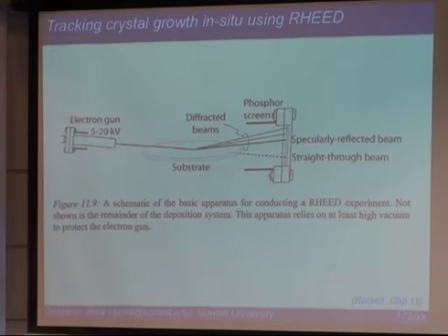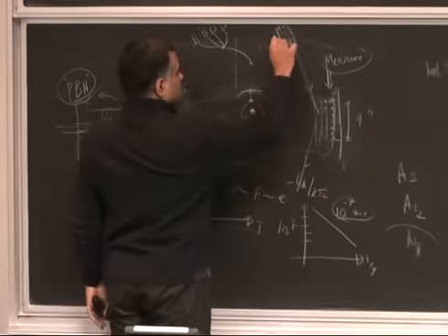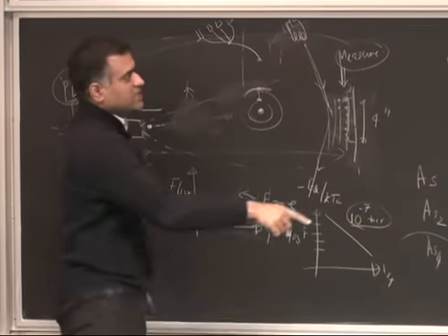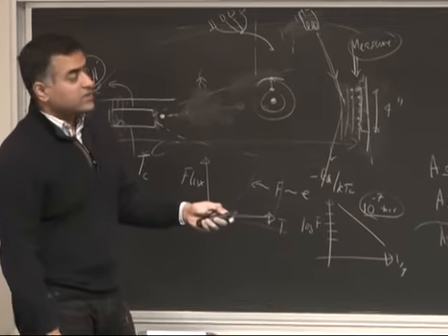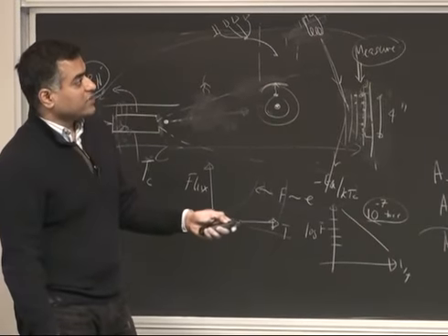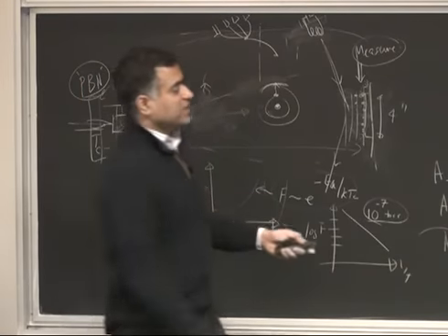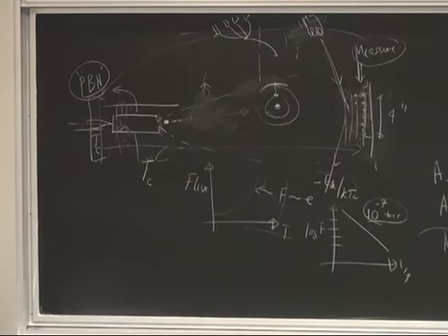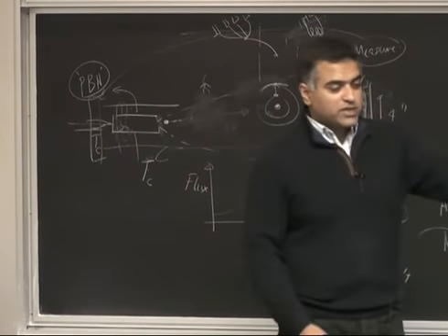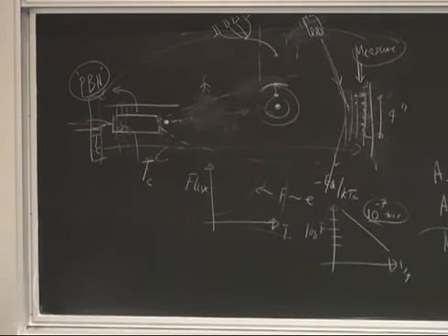So there's a wire here, and you're applying about 5 to 20 kilovolts of voltage across the wires here. Basically the wire would be sticking inside the vacuum system, inside the growth system. So this part is in ultra high vacuum, this is outside. So you have a little voltage, and then you apply 5 to 20 kilovolts and the electron beam comes out, and again, just like the atoms, it has nothing to collide with because it's vacuum. The mean free path is very long, right? And so it keeps going, and then it hits the substrate because that's where it's pointing.